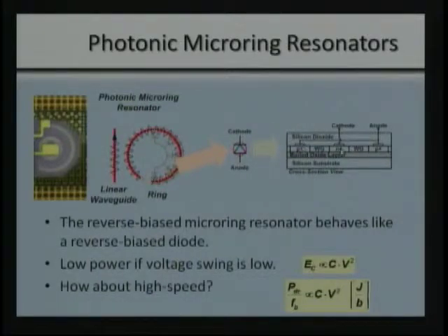By applying a voltage across here, you basically change the phase velocity around this ring. And so at one critical frequency, light that's traveling down this waveguide will be coupled into this ring. Okay? So it acts as a kind of resonator from an electrical engineer's standpoint. I'm not doing this justice for optical scientists, so please forgive me. But from an electrical standpoint, it's a high Q resonator. And at just the right wavelength, light will jump into this ring and become stored in the ring.